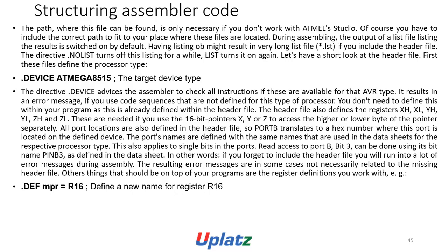Read access to port B, bit 3 can be done using its bit name PINB3 as defined in the data sheet. In other words, if you forget to include the header file, you will run into a lot of error messages during assembly. The resulting error messages are in some cases not necessarily related to the missing header file.